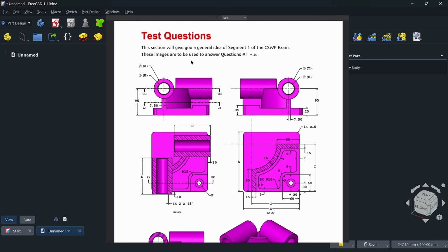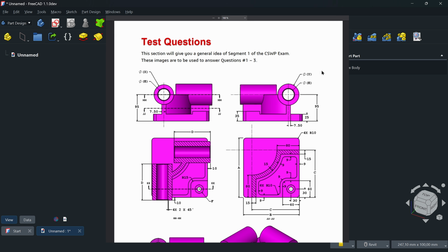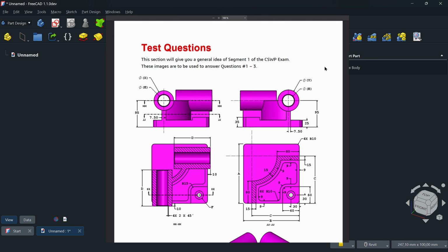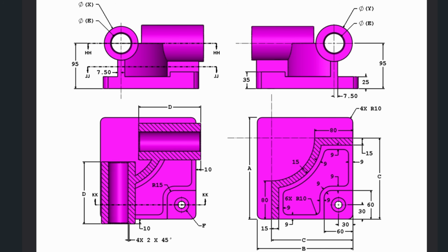The first thing to do is take a good look at the part, because the first question will be to recreate it. Since this is a time test, and given the shape of the part, you need to quickly identify the key features of the model. Looking at the dimensions, you'll see that some are numbers and others are letters. The ones labeled with letters represent variables. We'll be asked to modify them later so our model updates dynamically.